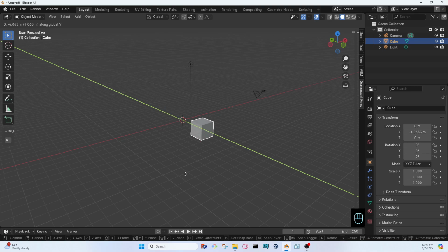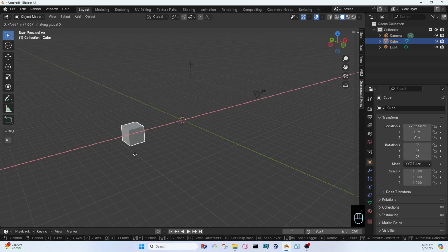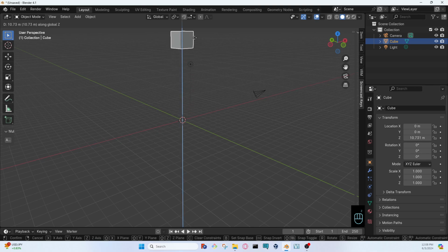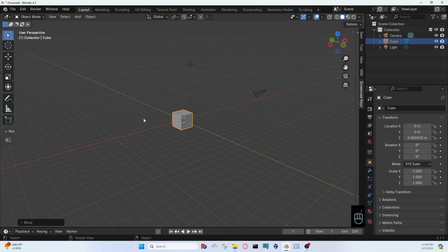Same thing with X. You can change while you're in the middle of snapping. If you decided you were on the wrong line, it happens all the time because you're turned around and not paying attention, you just hit the next axis that you want to interact with, and you change that one. I'm going to go to the Z. So the Z-axis, we'll snap them back.